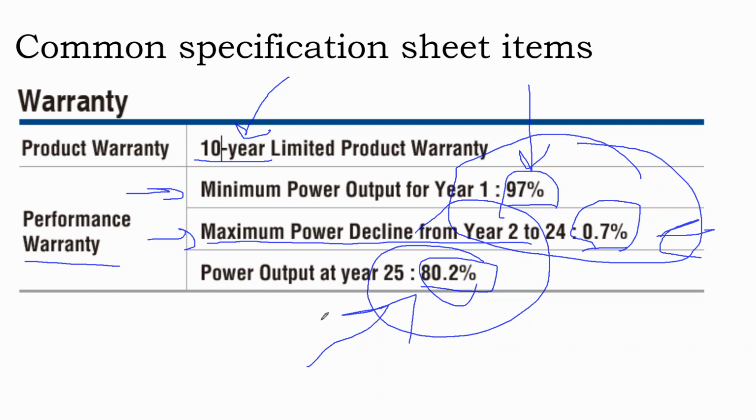So they say, look, if you're installing the solar array under a standard job site with good workmanship, nothing weird going on with your environment or with your design, then you can expect a 25-year life out of the system, that at year 25, the panels will still be doing 80% of what they do today. And that's where the industry debate is today: what do we do at year 25 when the system has paid itself back, made the customer a return on investment? Will the system start looking obsolete or not? And you got two different answers.